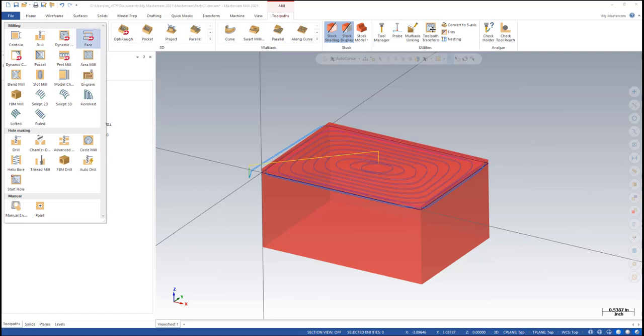So you can use an algorithm in the software that attempts to maintain radial engagement. A lot of these tool paths, especially in the 2D that are here, just look at a shape and use a traditional approach to covering the area. And as you approach corners or something like that, your radial engagement on your tool is going to dramatically vary.